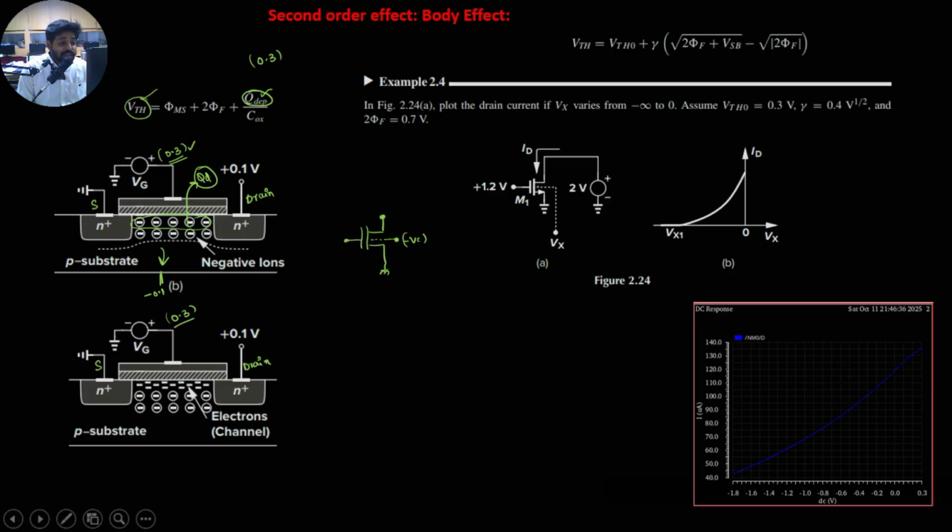As per the theoretical concepts, when a larger amount of negative charge is left behind, then to form inversion, to bring the electrons into that part to form a channel, more voltage is required to attract that extra charge. So it needs around 0.4, previously 0.3, where the electrons are left over here for this part.